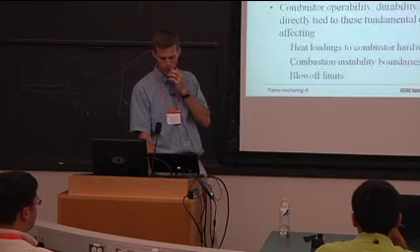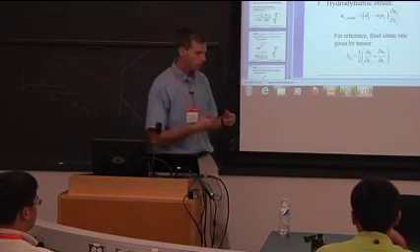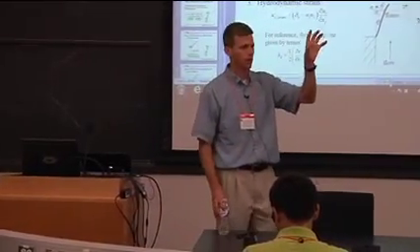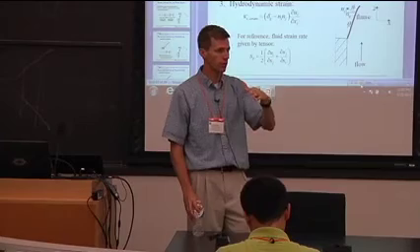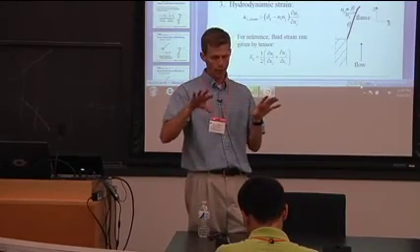Oh, it was in the previous. Okay. Anyway, in the previous, if you remember, I drew that bifurcation diagram of a swirl flow where I said you always get breakdown, you're in the hysteresis region, and you never get breakdown. So a low swirl burner operates in the region where you're never breaking down.